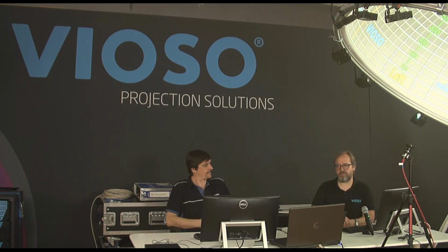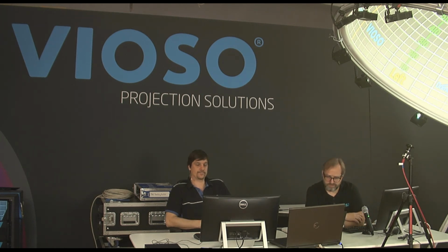If you go the Vioso way, and if the camera has not moved, that's the key. If the camera is still in place, you can simply scan a single projector and calculate it back into the existing compound of the other 12 projectors. Again, the key is that the camera has not moved. Assuming a fixed setup with fixed mounted cameras, this is the standard way, of course. So the question is answered that way. In the Vioso way, you can just scan one if you have the camera still in position, and otherwise, without leaving Pandora's Box, you can do manual adjustments there.